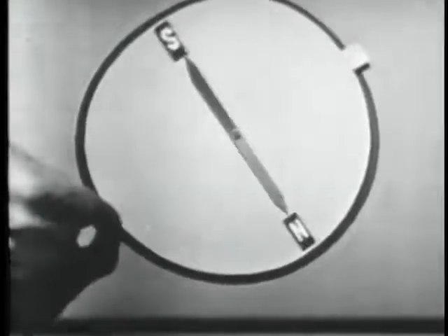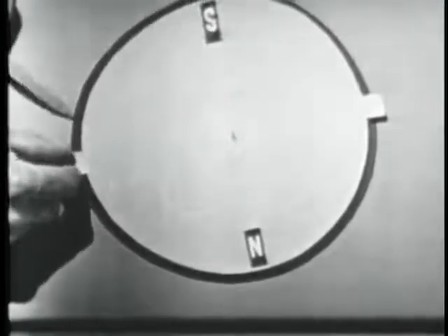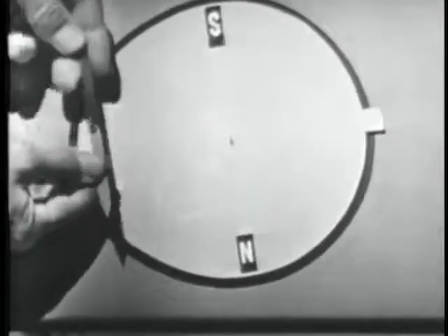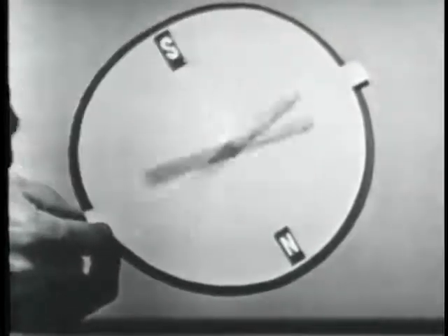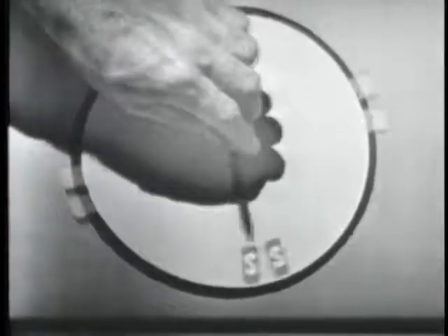Now, there are several types of induction motors, but they all operate on the same basic principle, which can be illustrated like this. Okay, what we have here is a cardboard disc, mounted on a pivot, by the way, so that we can spin it, and we have 2 permanent magnets glued to the disc. Thus, if we spin the disc, we have a rotating magnetic field. Now, the principle we want to show you here is that if we take another magnet, such as this compass needle, and put it on the pivot, so it's free to rotate, and we spin the cardboard disc, we have a rotating magnetic field.